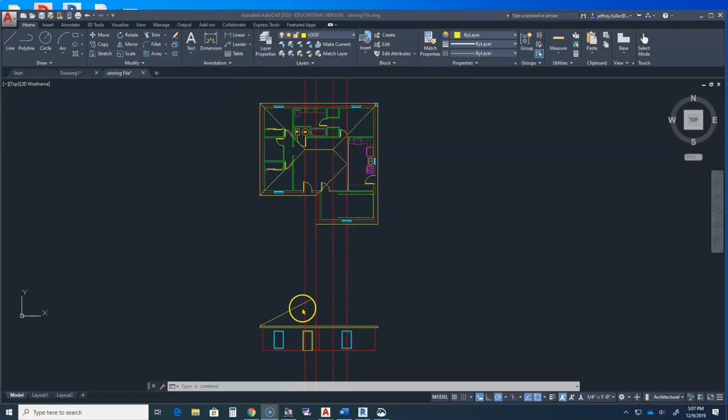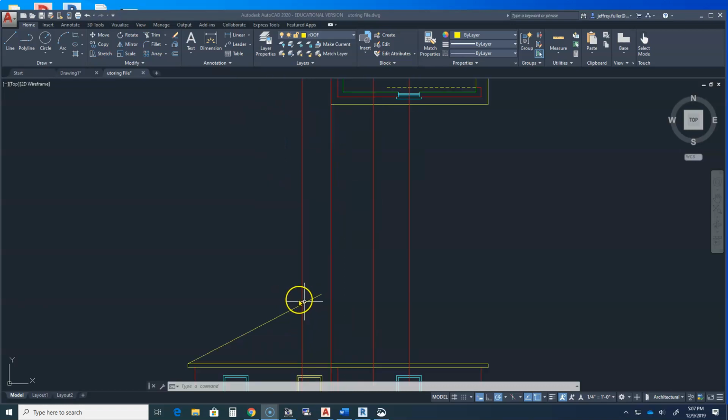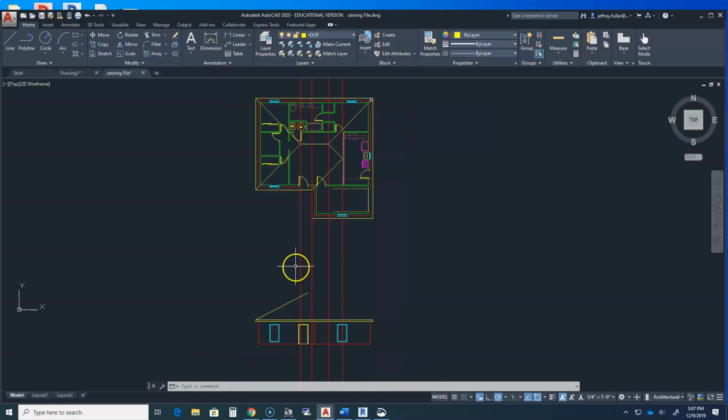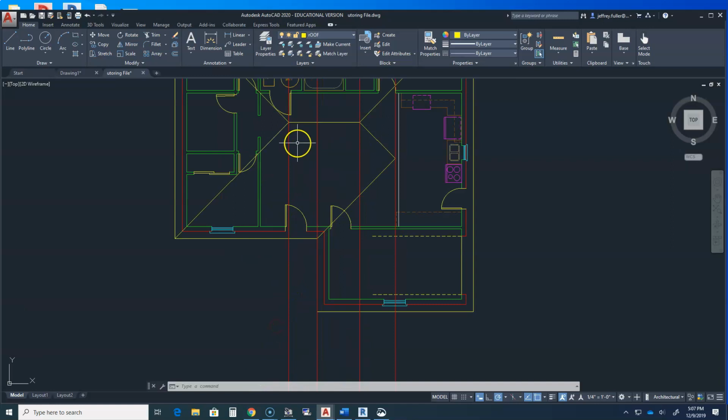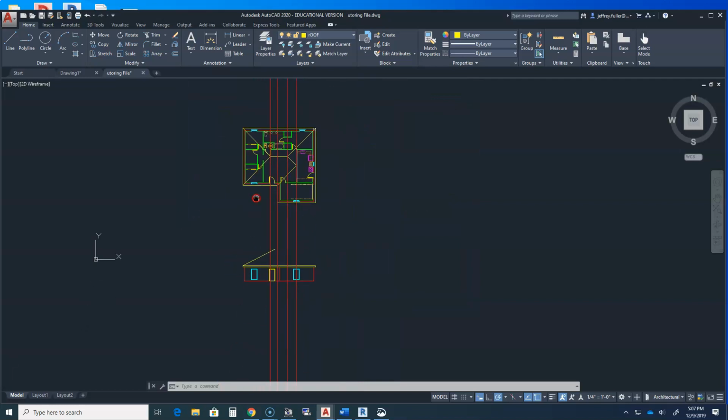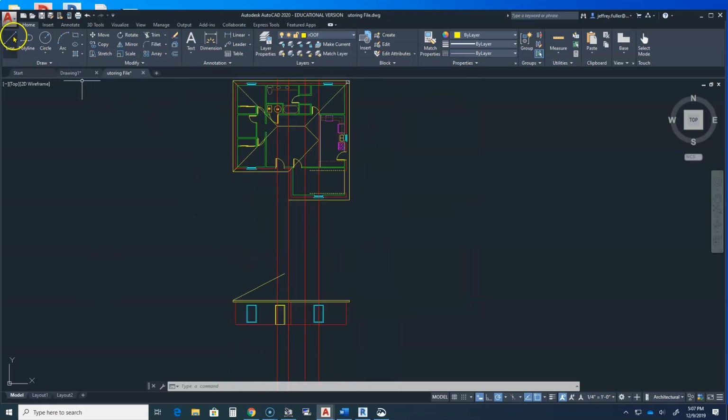Now we know where the main ridge line of the roof will be. It will be at the intersection of the west slope line and the west apex construction line. If we look at the plan view of the roof, in this example, we can see that the main ridge line runs at a steady elevation to the east apex of the roof, marked by this third construction line. So from the intersection of the west apex and the west slope line, I will draw a horizontal line across to the east apex construction line and stop.